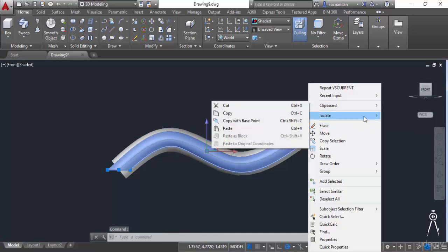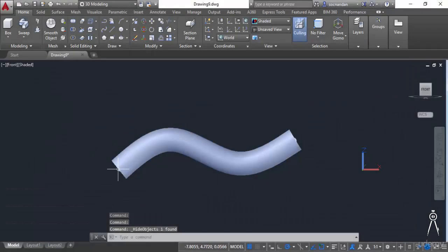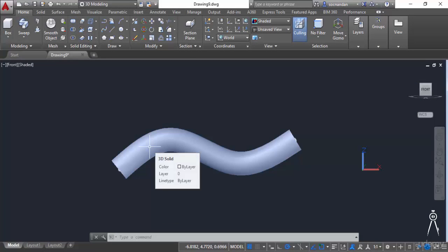Now when you compare both these geometries, let's hide the former one so that you can clearly see this. Now in this geometry you'll be able to directly see that the original geometry which was on the XY plane is maintained, but the path is not perpendicular. So the original path has been followed and the geometry has been made as it is. In this case, the path which goes something like this is perpendicular to the initial circle. So this circle is perpendicular to this, and we have selected the respective option in alignment for making that. So that's the difference between aligning the path perpendicular to the original geometry and not aligning it.